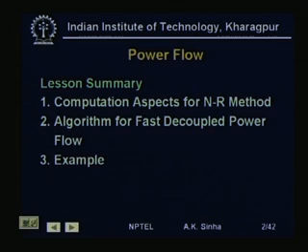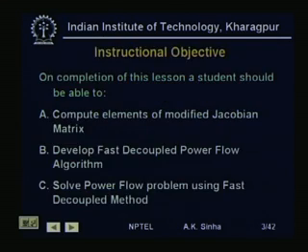Then we will develop the fast decoupled power flow algorithm, and we will take up an example for solving a fast decoupled power flow problem. On the completion of this lesson, you should be able to compute elements of the modified Jacobian matrix, develop the fast decoupled power flow algorithm, and solve a power flow problem using the fast decoupled method.